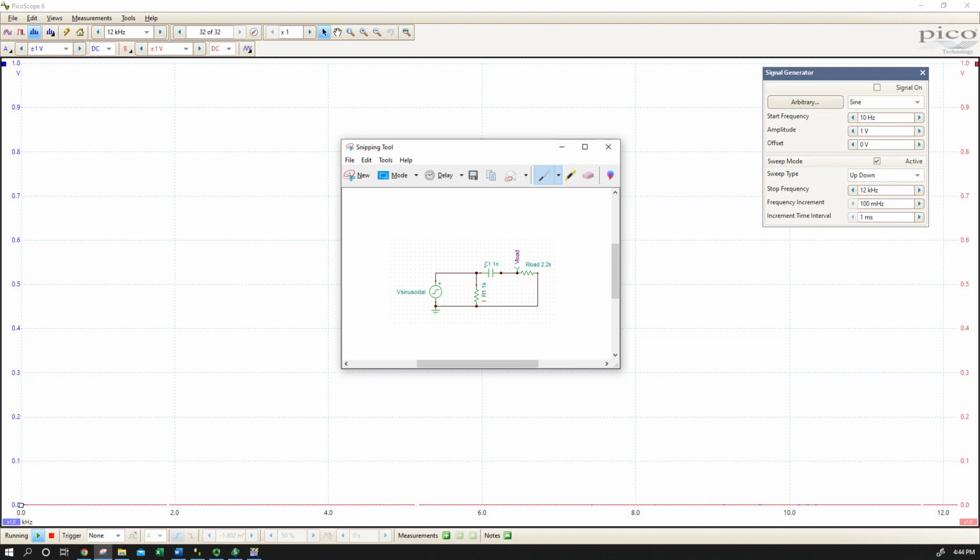Hopefully you can see my cursor. So I have the same sinusoidal voltage source, and in the branch that includes my load resistor, I've swapped my 0.1 Henry inductor with a 1 nanofarad capacitor. So the small capacitance, it's in the denominator. It's going to give me a fairly big response as I sweep through frequency. I'm going to end up having a fairly big